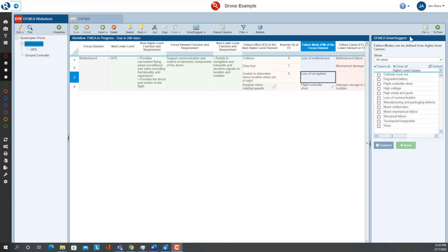SmartSuggest video first. Relyence FMEA SmartSuggest helps to ensure that your FMEA data remains synchronized throughout your analysis tree hierarchy. From the SmartSuggest panel, you can see recommended data suggestions, then choose those that are most appropriate for your analysis. In addition to suggestions for failure modes and effects from higher-level cause and failure mode data, SmartSuggest can also highlight warnings, which identify cases where FMEA data is not in sync across analysis tree levels in the FMEA worksheet. Data may become inconsistent across worksheets if the analysis tree hierarchy is modified, as well as if identified next higher level functions are changed.